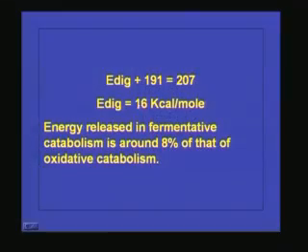So that's what I told, the catabolism or these metabolic processes, whatever is happening in anaerobic process, it is having a positive effect as well as a negative effect. But how can we overcome this? If we can maintain high microbial concentration in the system, we can reduce the hydraulic retention time. So that we will see afterwards.